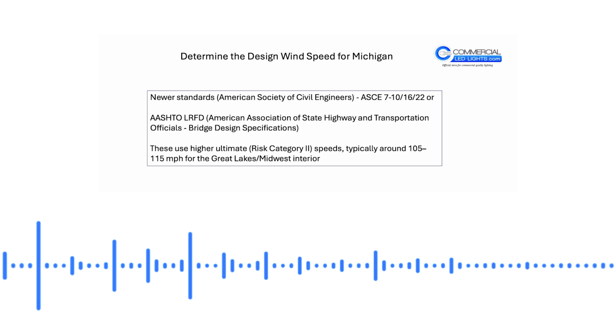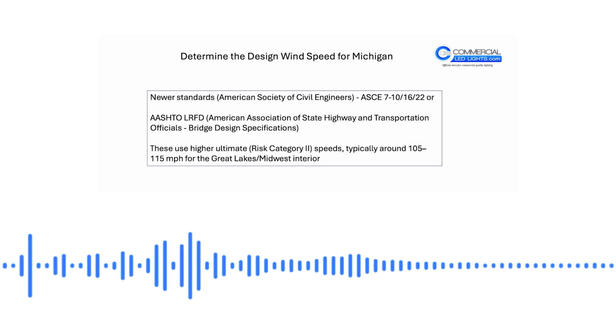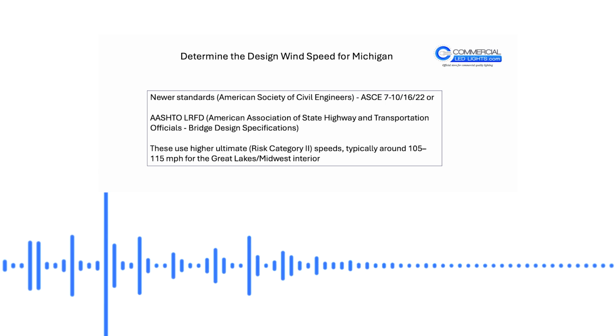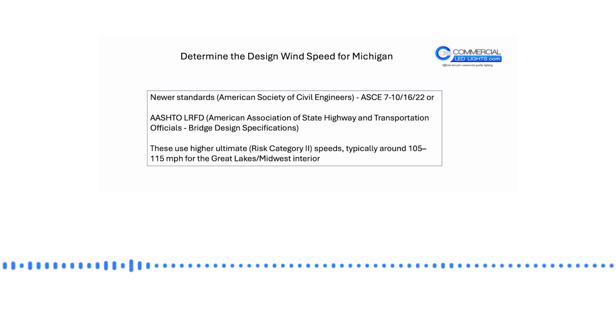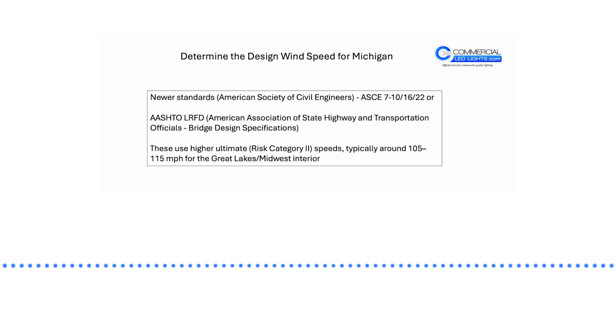So the next step, like Peter mentioned, we've got the design done. We understand how much pressure is going to be on these poles, given the area of the light, which is really important. It's less weight, more area. You have to determine the wind speed in the area wherever these are being installed. And there are resources that, with zip codes, cities, a variety of ways, we can find out what the maximum wind is in that area. So from that point, we are going to be designing the light to that maximum wind speed.